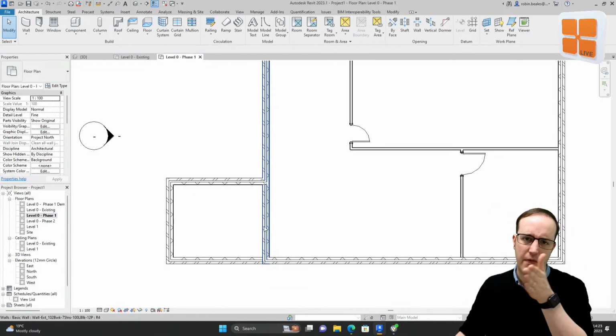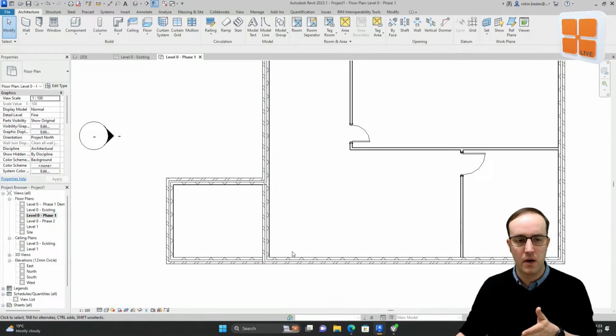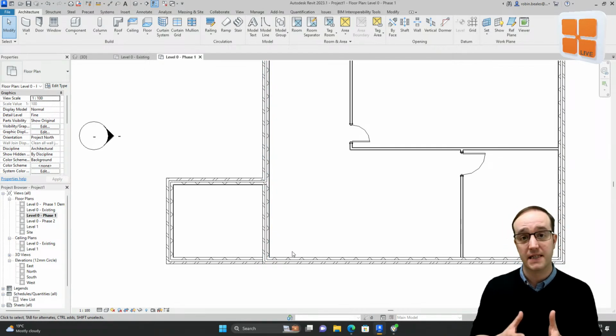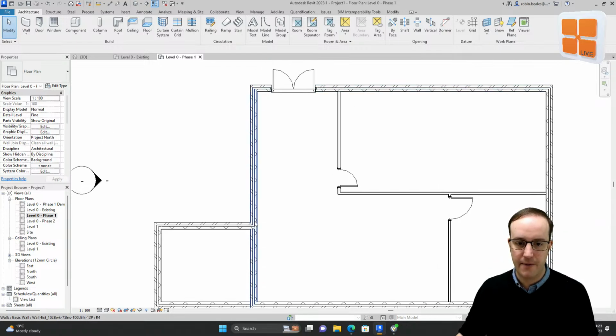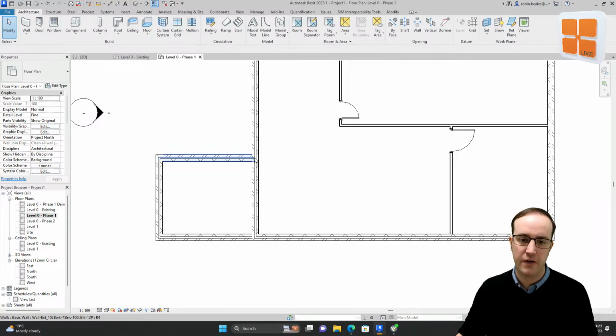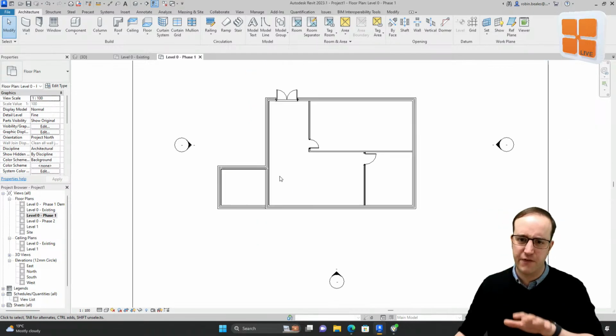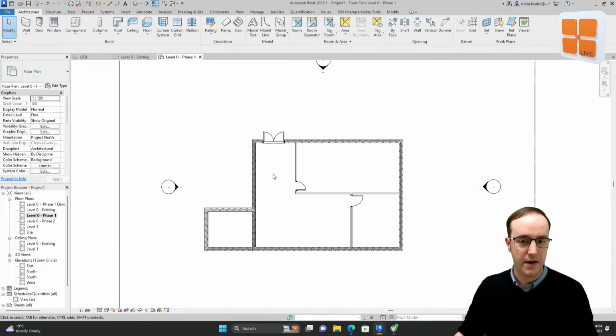So just think about the way in which you position that workflow. Sometimes you have to draw the geometry in a certain way to have Revit understand what it is. Okay, so what works quite nicely is if I was to draw the wall from here to here, turn off joins, draw another wall. Yes, they are in the first phase, but then we can demolish this part of the wall in phase one and either create a new one with an opening or just put the opening in it. Okay, so it's just some different types of workaround, but it works quite nicely.